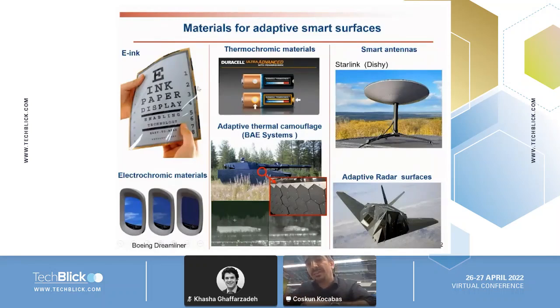If you go to longer wavelength, infrared, there are some military applications. Camouflage is one of them. Can you hide the visibility of a military vehicle? Can you do it dynamically by changing the infrared radiation from the surface? An easy solution is, if you control the surface temperature of an object, you can change the appearance of this object in infrared imaging systems. And BAE is developing this technology by cooling and heating up the surface temperature.